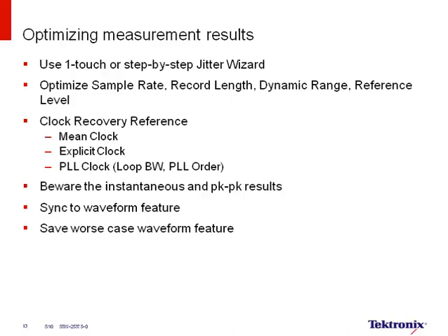However, there are two issues with this. Number one, the mean clock is not how the standards and how the silicon works. And number two, sometimes if you have high levels of low-frequency modulation, for example, if your system implements spread spectrum clocking, the mean clock cannot create an open eye. In that case, you have to use a reference clock.